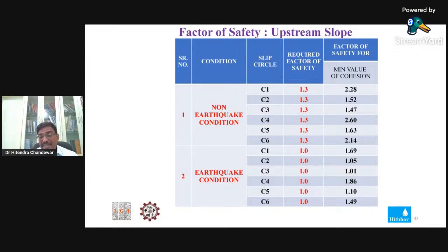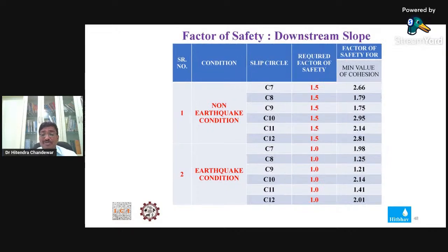So within 125 hectare, I had to do all my business, because if you go with a flatter slope, then my bottom width requirement is more, and my storage would be less. In such cases I have to increase the height of the earthen dam. Then again it's a very costly affair, and again a stability issue. So my job was to provide the most optimum design for the client.